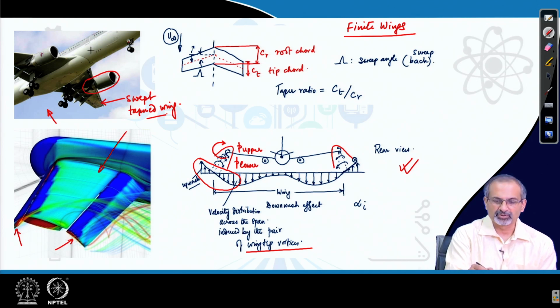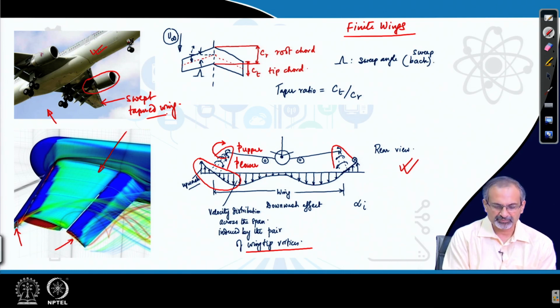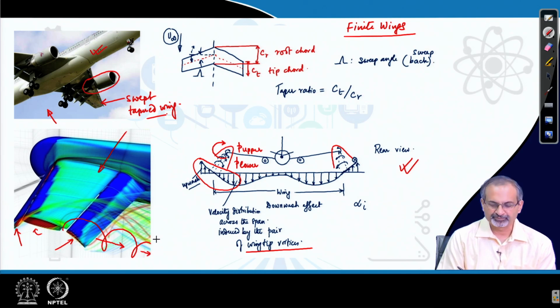So, it is similar to a situation like this, and then here are some instantaneous streamlines which can give you a feeling that the flow is tending to roll up from the bottom, and it is also creating a kind of spiraling flow downstream, which is because of the roll up and its consequent advection into the wake of the wing.